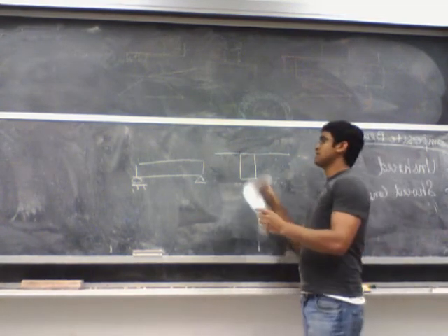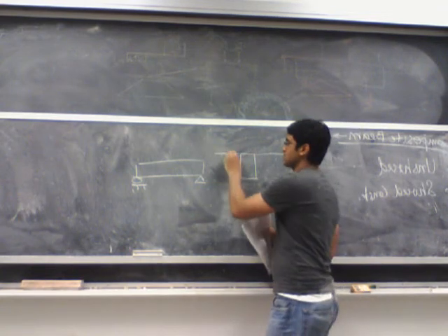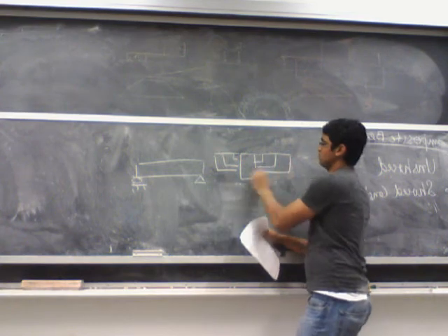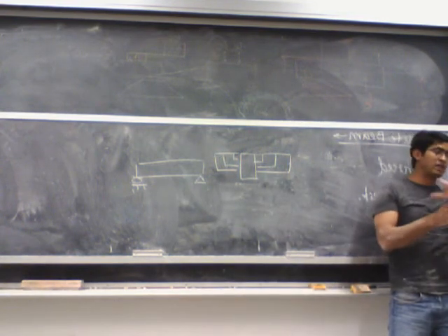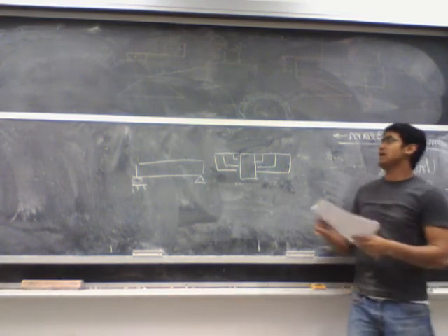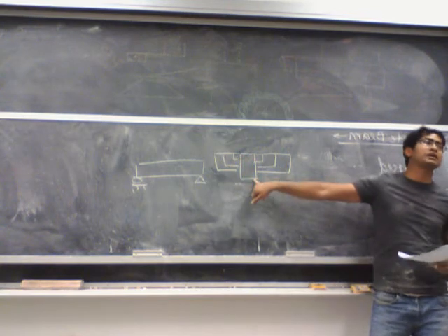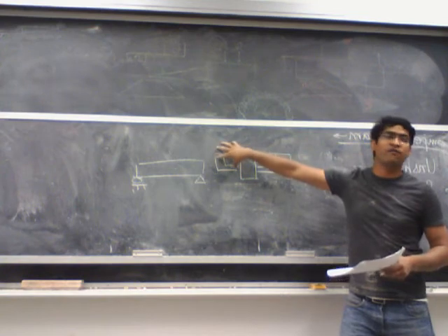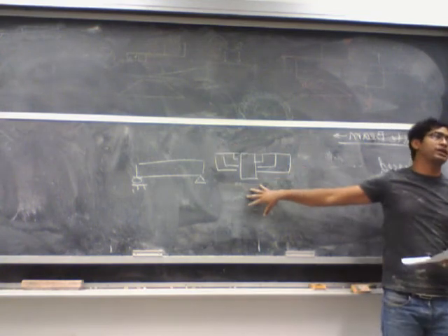The only difference is, in case of an unshored construction, this formwork, which gives the slab a certain shape, is actually connected to the girder itself. So if I apply any load on the formwork, it gets transferred to the girder.